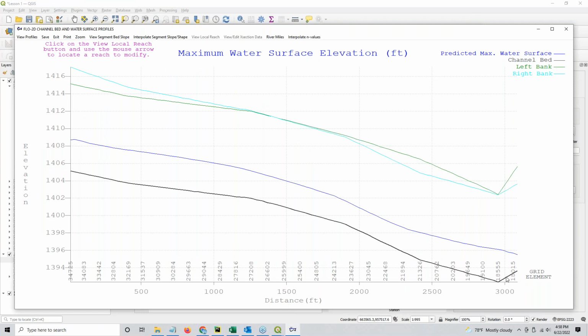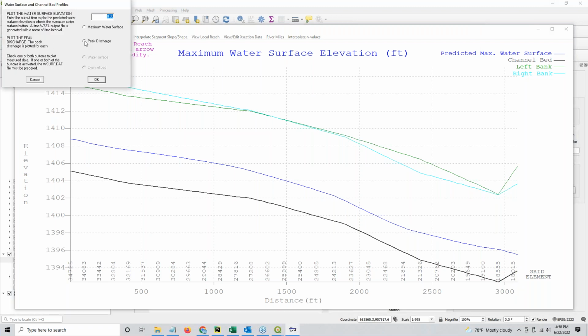Oh, a little bit of something going on right here. So be careful of that kind of stuff on a trap channel, because on a trap channel, the bed elevation comes from the bank elevation, the lowest bank elevation minus the depth. So we need to make this one deeper. That is 18015. Let's check the next one.